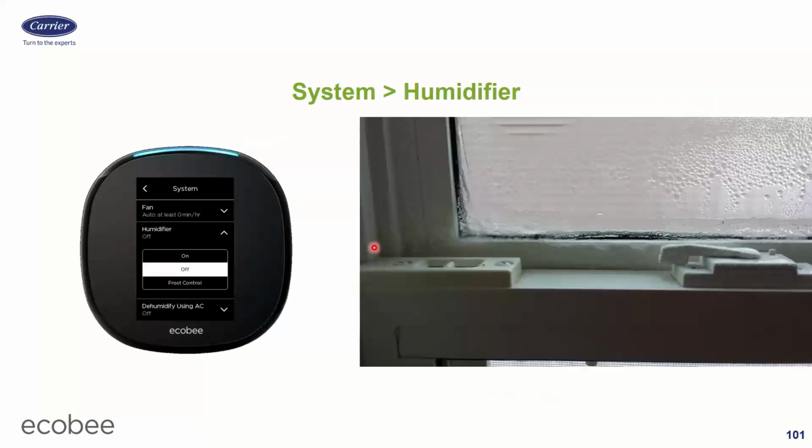Below the fan setting is the humidifier setting. For whatever reason, it's defaulted off. I don't understand why. You just bought a humidifier, you installed it, you configured the stat for a humidifier, but it's defaulted to be off.